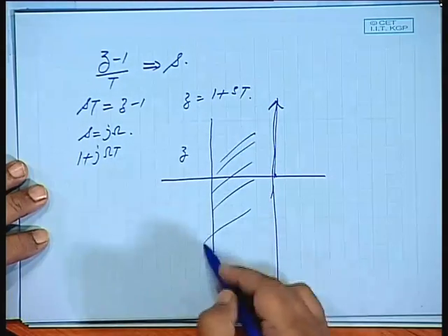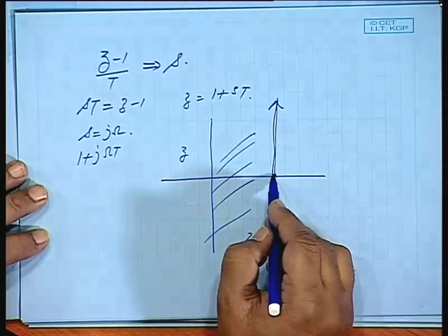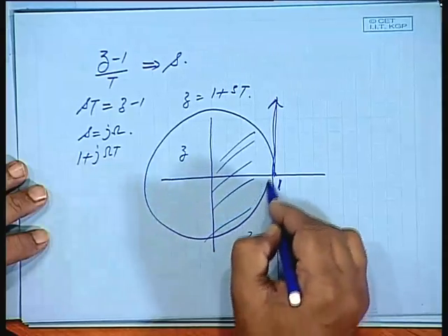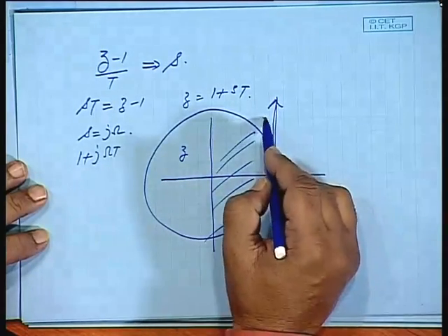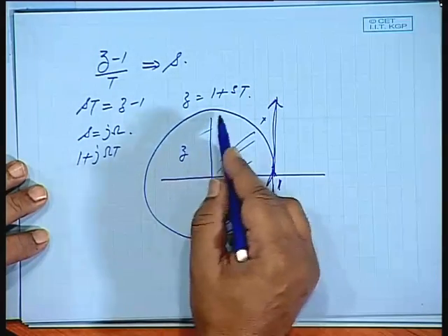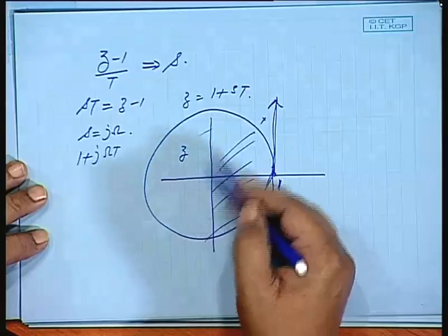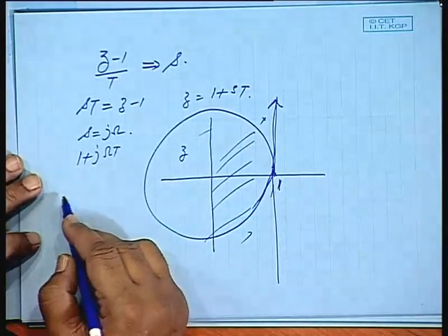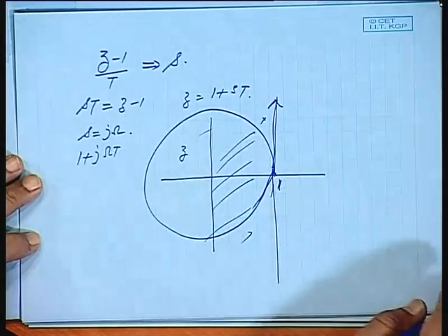the imaginary axis. So, this entire region is stable, but actually the stable region is only this unit circle. So, you are feeling you are safe, you are in the stable zone, but actually you are not so. The actual stable zone is this much. So, it is highly optimistic. This is also not a very correct estimate. The earlier one was pessimistic, but it was guaranteeing stability of the system. This will not guarantee stability of the system.